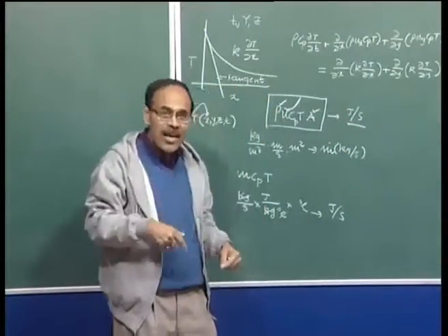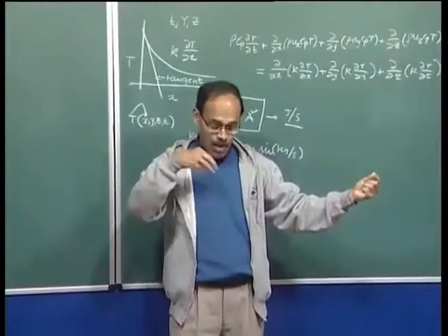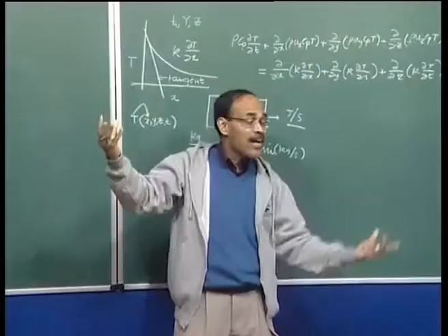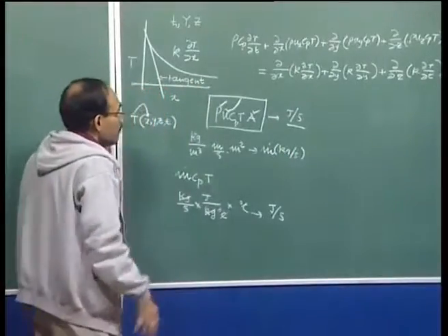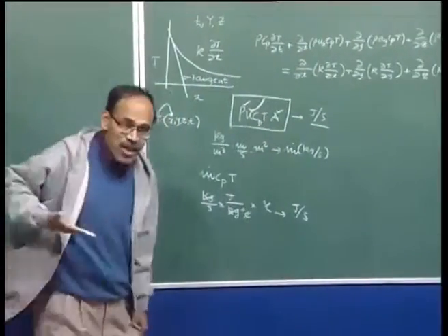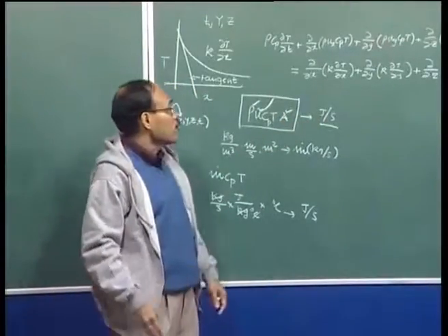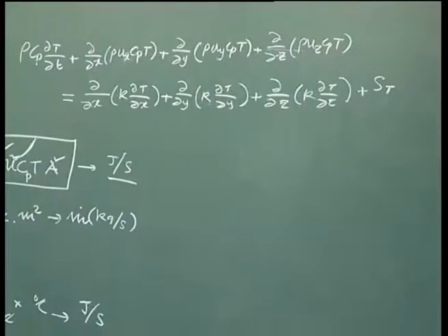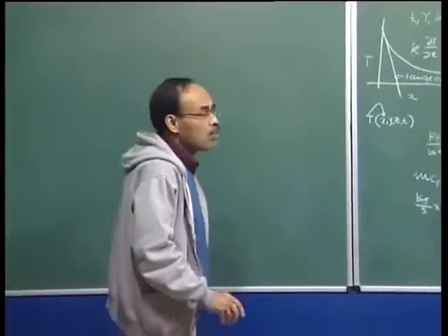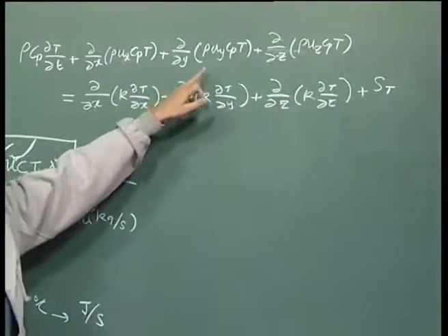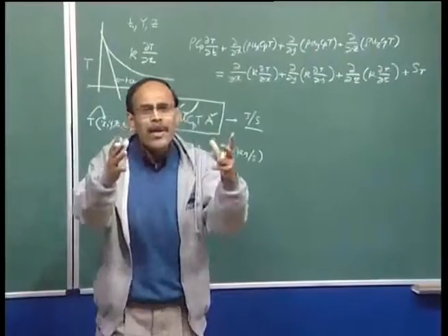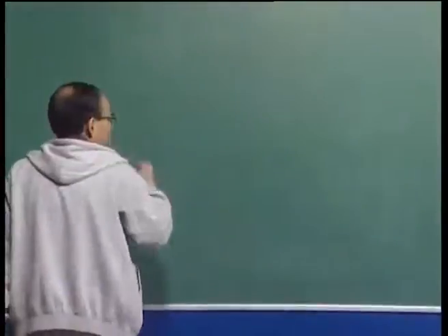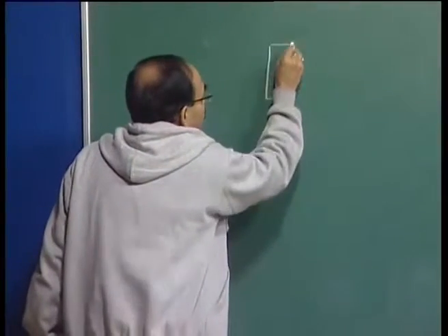But on the other hand, if I am standing here, if I hit this point and this point, my temperature may depend on at what rate I am hitting here, at what rate I am hitting here. Okay. So this is basically the second order derivative, and what I have said about the nature of the flow in one single direction, that the downstream point has no role, is reflected in the first order derivative. Now solving this equation therefore will require, I have to solve for the ux, uy and uz field. So solve the velocity field first and use that velocity field to solve this particular equation. So it's a cumbersome task. Now let us imagine I have a solid. What is my objective? I have a solid which I have immersed into liquid.